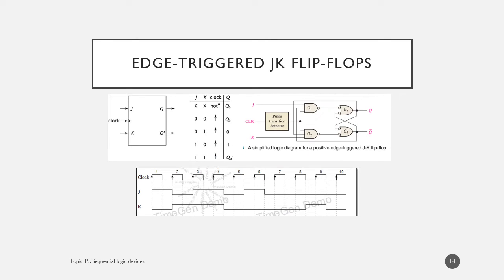Okay, now let's look at some other flip-flops. The JK flip-flop in many ways is similar to, if you remember, the RS latch. But it's a flip-flop, so it's an edge-triggered device. You can treat J as the set input and K as the R input. This will help you remember the truth table, or state excitation table, whatever you call it.